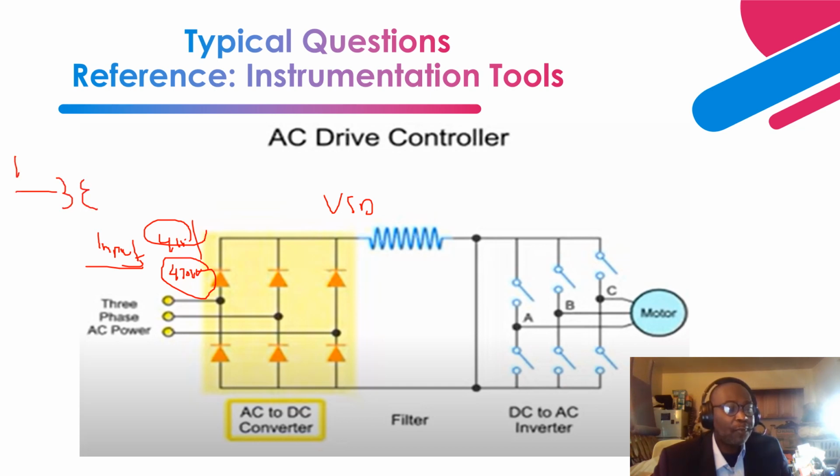Okay, so let's say from 13.8 kV, 34.5 kV, whichever transmission level or distribution level voltage that you have, right? You step the voltage down to a voltage that is required. That will be very good for the variable speed drive as an input voltage. The input voltage for this power electronics is very low voltage, 415, 430 volts.